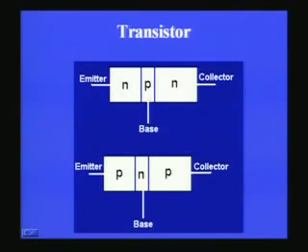Only at absolute 0 there won't be any holes. At normal temperatures, due to intrinsic conductivity, there will be a small quantity of holes present in the N doped semiconductor in the first region, and therefore the electrons are called the majority carriers and the holes here are called the minority carriers for obvious reasons, because the holes will be very, very small in number compared to the electrons.